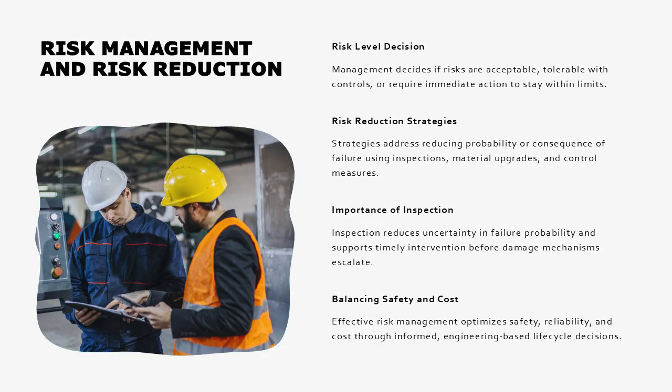Risk management in RBI involves deciding how to address identified risks to ensure they remain within acceptable limits defined by the organization or regulatory requirements. Once risk levels are determined, management must decide whether the risk is acceptable, tolerable with controls, or unacceptable and requiring immediate action. Risk reduction strategies may target the probability of failure, the consequence of failure, or both.